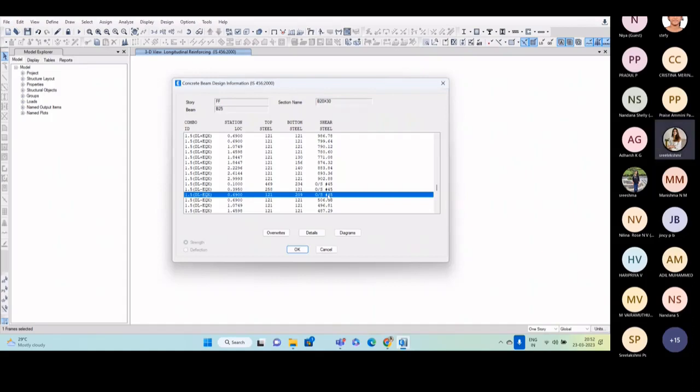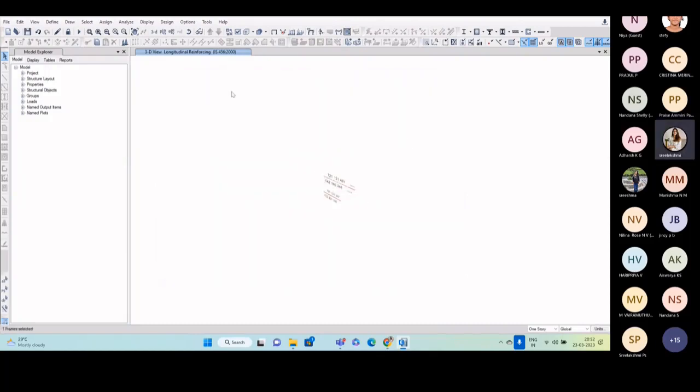All of you know the formula for shear stress. So tau V is Vu by bd as per IS code. So if the section of the beam increases, that means Vu by bd, if the depth of the beam or if the b or d, if we increase any of the sections, the shear stress may decrease. So we'll just try making the section size increase.